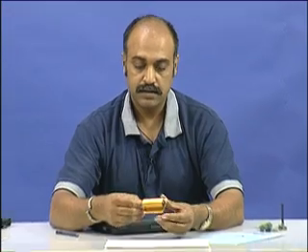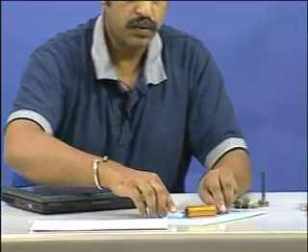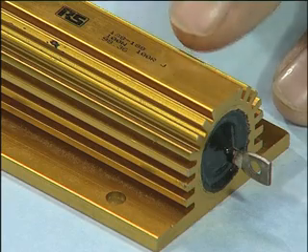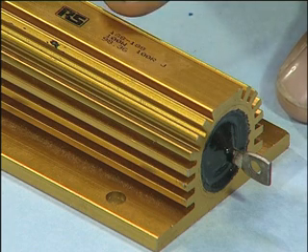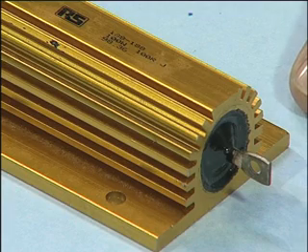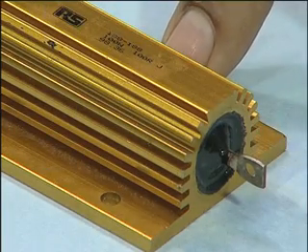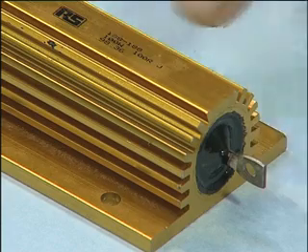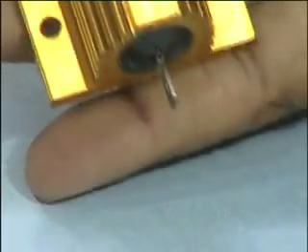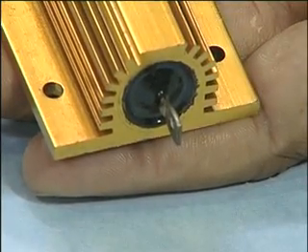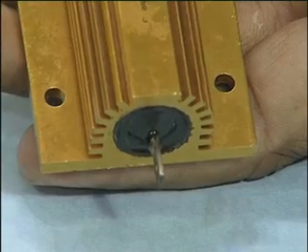Another high wattage resistor, which is actually of similar size compared to the 25 watt resistor that you saw just now, is something like this, which has a heat sink also. You will see the two terminals here and the value written on it, 100 ohms, and it is a 100 watt resistor, which is 4 times the power dissipating capability of the previous wire wound 25 watt resistor, but of similar size. It is basically because of the heat sink encapsulating the actual resistor, which can dissipate the heat more effectively, and this has 4 mounting holes which can be mounted onto another aluminum base plate or a base metallic sheet, which can dissipate the heat much more effectively.